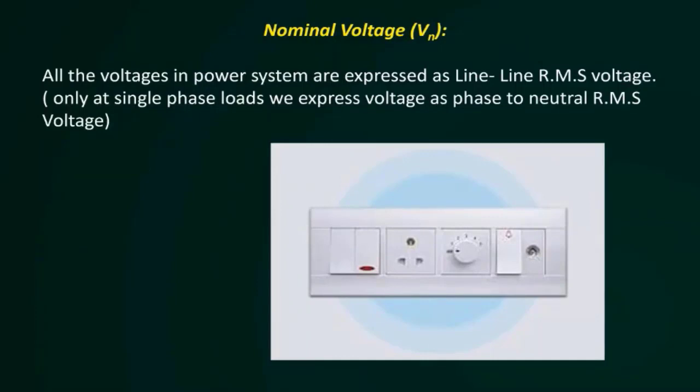If I say nominal frequency, what is the frequency that we are supposed to get in our households, industries, or for all our electrical appliances? 50 hertz. We are supposed to get 50 hertz frequency for all our loads from the utility. So the value that we are supposed to get is called the nominal value.